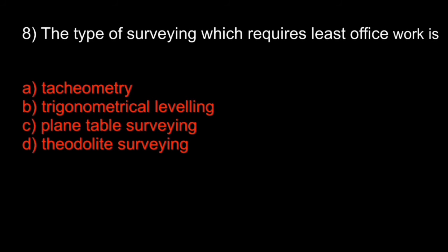Now, the last one is theodolite survey. Theodolite is the most accurate instrument used for measurement of horizontal and vertical angles. It can be used for various other purposes such as laying off horizontal angles, locating points on a line, prolonging survey lines, establishing grades, determining differences in elevation, etc.